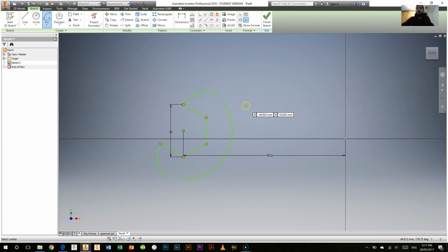There's a couple of different ways I could do that. I can do it like I have there, where I haven't actually put a specific dimension, I haven't connected it to these side ones yet. Or I could have connected it straight to them, but then things might have gone a bit funny in my sketch because we haven't actually given these a correct length yet. But perhaps we'll try that. Let's delete it and let's do it as a center point and connect it onto those end pieces there. So there we go, we'll connect it there, and oh, you see that doesn't quite connect right there.